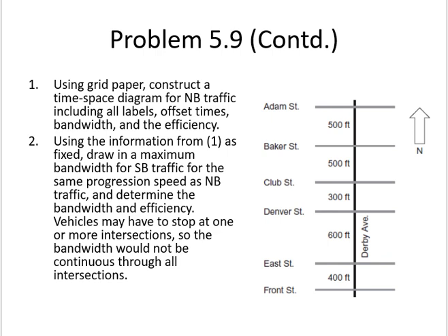So first thing is I'll calculate the phase time. Or we can start with the calculation of the offsets, because we know the speed, we know the distances. So tell me the offsets. The first offset will be 500 plus 40, 540 divided by the speed, which is 30.